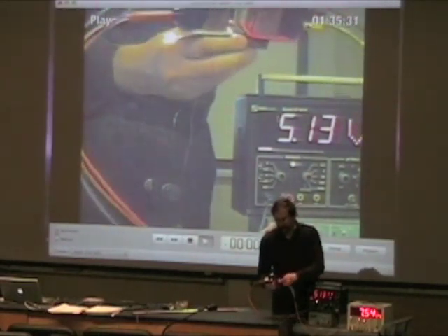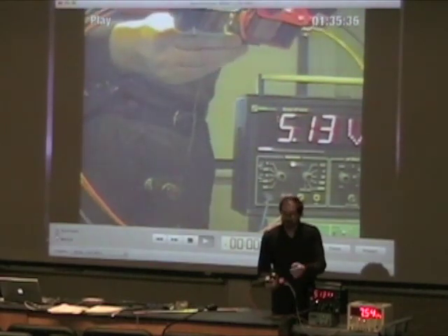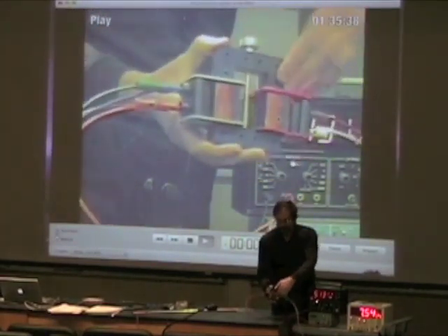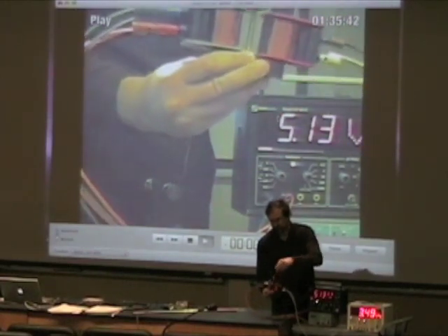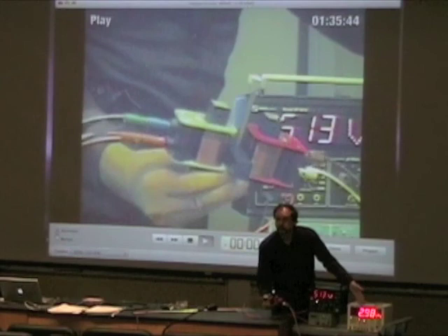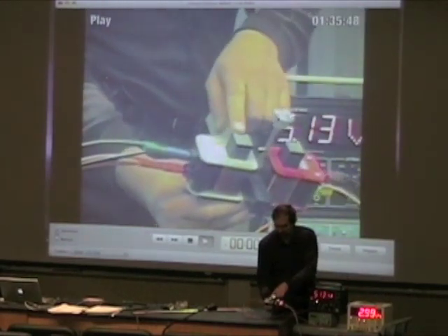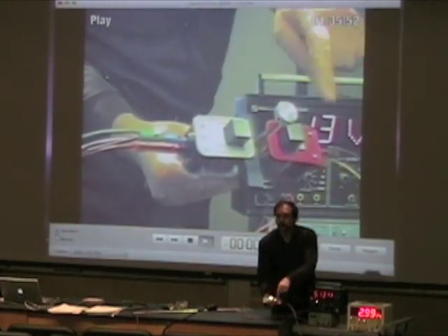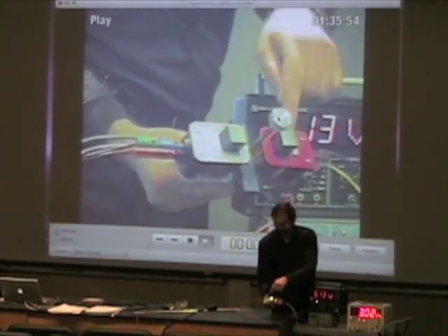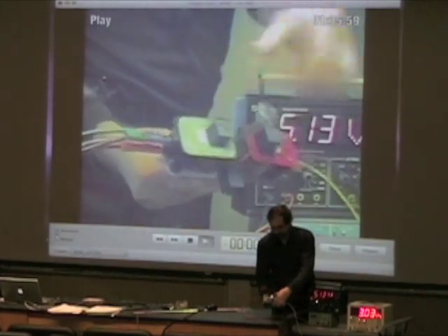In this particular situation, for example, not all magnetic field is concentrated inside this. Actually, if I open this transformer, we can see the voltage drops. Why? Because now magnetic field, which is generated by this coil, doesn't go completely in that coil. So this flux is much lower now than this flux.